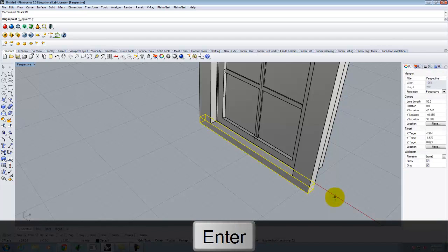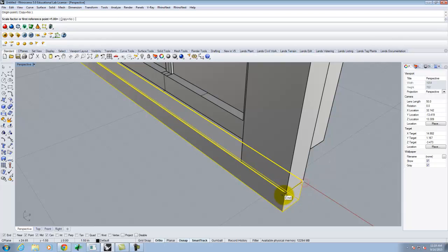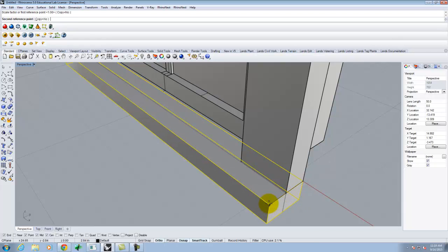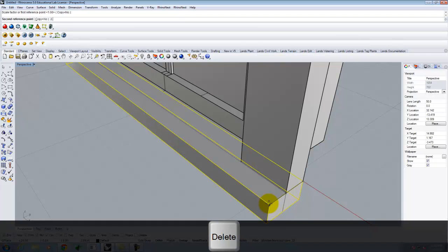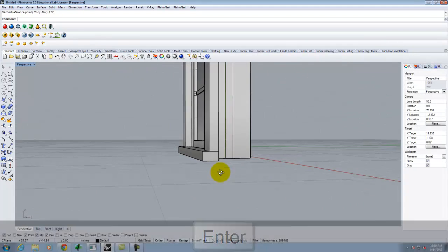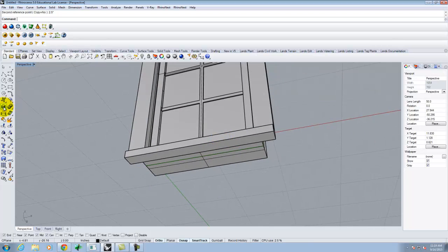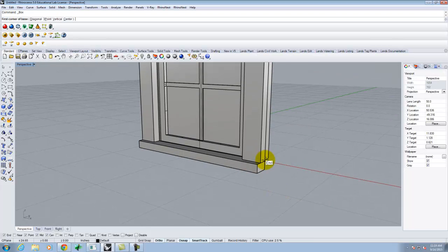So again, these are all the things that I've done over the last 4 or 5 classes. It's just the same stuff. It's just assembled a little bit differently. Right? So let's scale this so that it's maybe an inch and a half. Let's go 2.5 inches, something like that. Right, I'm just building a little sill under the window, and then we'll do one more little piece.